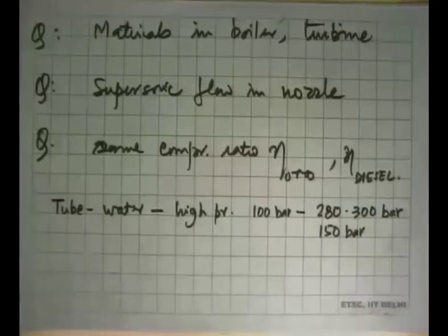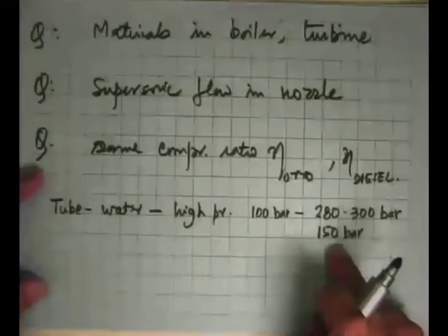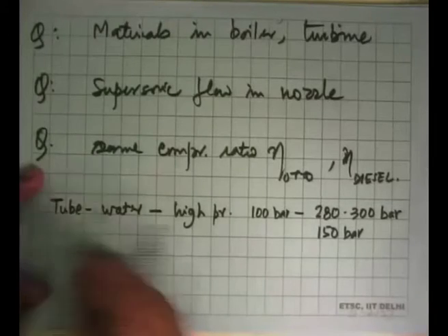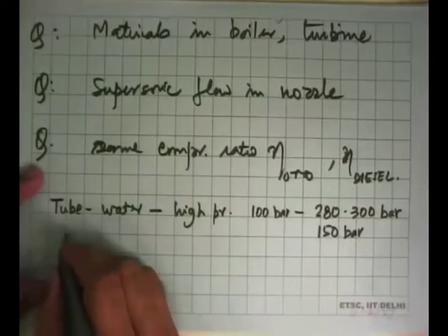The thing is, because you have such high pressures, we need to make the tube or the cylinder or the container small in diameter because of stress analysis. If you recall your solid mechanics, the larger the diameter, the stresses increase in proportion to the diameter, and the thickness of the wall that you require to make that device keeps increasing. So these devices which are at high pressures, if it's just a vessel or a tank, that is called a pressure vessel.